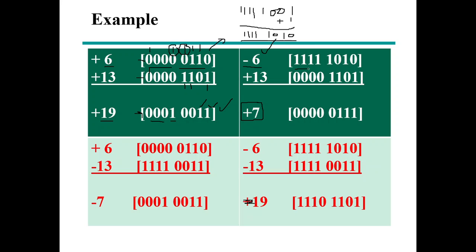You can verify directly if this is minus 6 or not. In 2's complement notation, the most significant bit's weight is considered as a negative weight. So this is minus 128. And the rest of these things should add to 122 because the final value is minus 6.